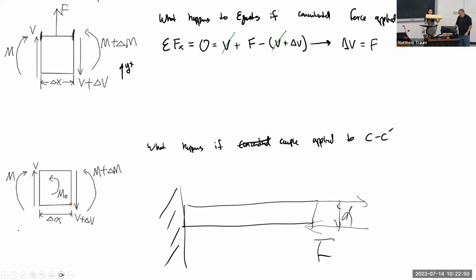So for external force applied, if you climb on this side and apply a transverse force, it will cause bending. It will cause the internal bending moment. You apply a couple at the free end or any cross section, it will cause the internal bending moment inside the beam. If the twist you mean is a couple, yes, it's couple, it's not torque. Torque is about rotation about the axial direction. There's no internal bending moment generated by torque, so it's only internal shear stress.